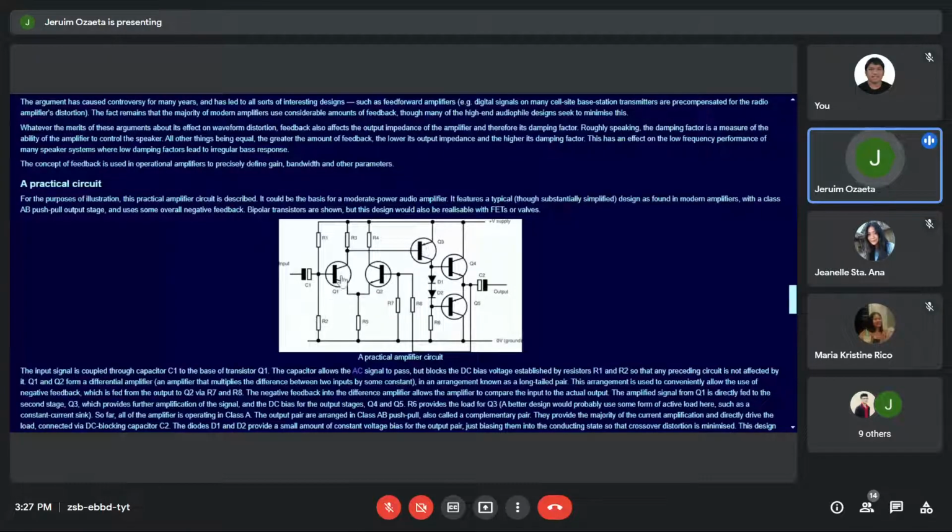And the output signal is ordinarily taken at Q1. So the input signal through C1 gets into Q1 and then output goes to Q3. Now what is the purpose of Q2 if that is bypassed? Q2 serves just to stabilize the voltage at Q1.